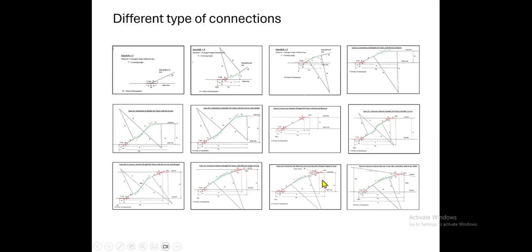And of course, the symmetrical split we have seen, which we normally provide in a snag dead end. There we are providing the loop line with one end of a symmetrical split. Of course the other line, suppose we have 1 in 12. Here also a straight connection is not possible, because both lines will have some deviation, so necessarily we have to introduce a connecting curve. So how is this to be designed?